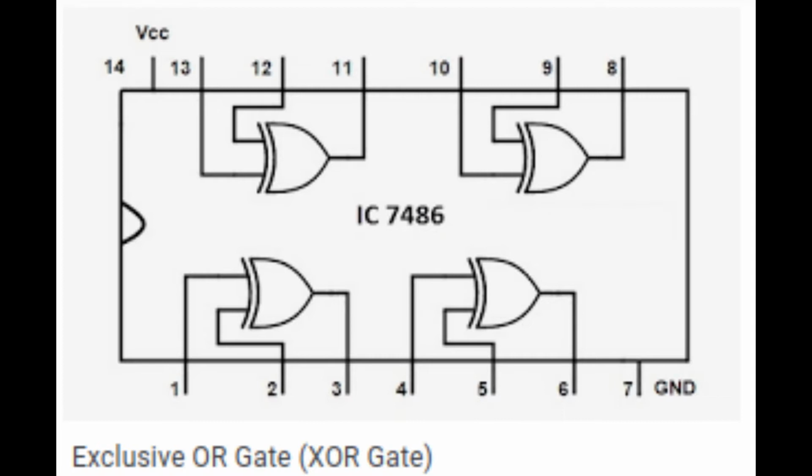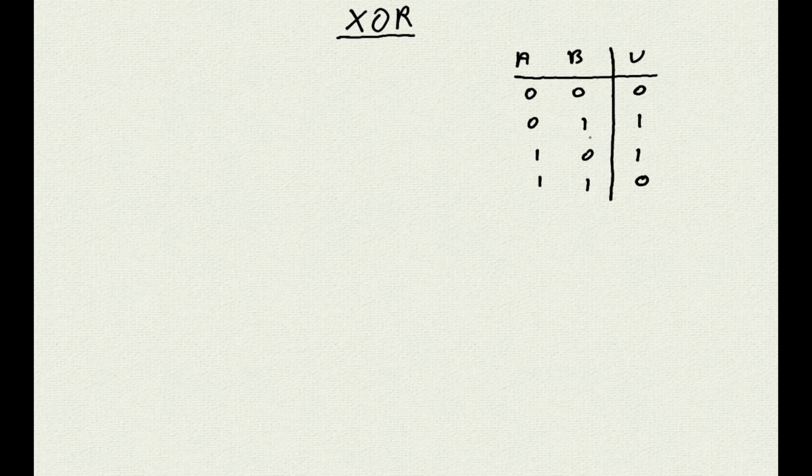Another way to say that the circuit provides at its output an OR operation, but exclusively if the inputs are different. Like they say, if one or the other, but not both. Let's see now how we can draw the schematic of such a circuit starting from the truth table. There are two methods to use. The first one is to look at the rows that have a 1 at the output. We will look at the other method in a later episode.